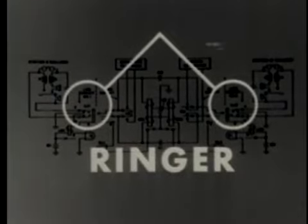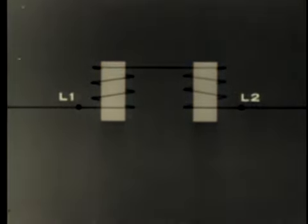The audible device is the telephone ringer, or buzzer. The telephone ringer works on the principle of electromagnetic attraction and repulsion. When 2 soft iron cores are wound oppositely with wire, they become electromagnets whose polarity will change as the current in our line alternates.